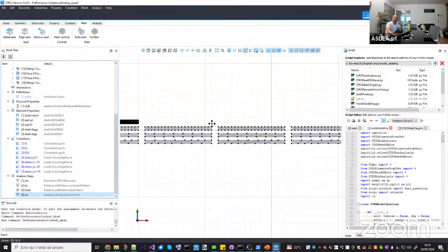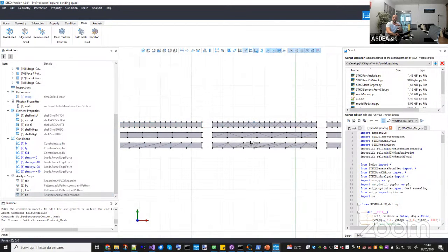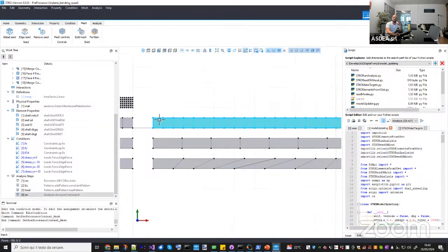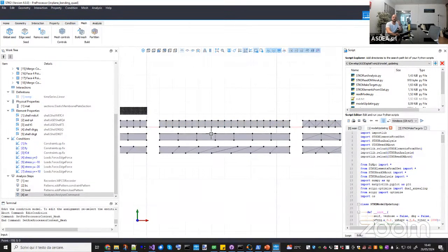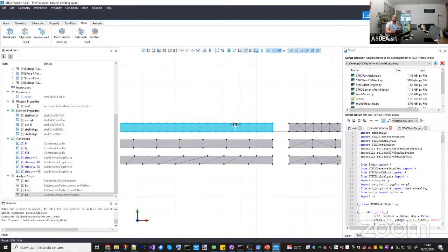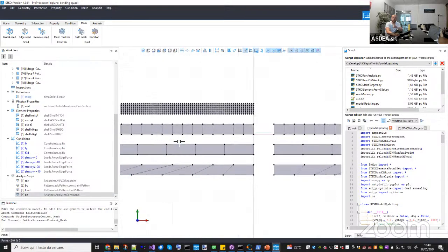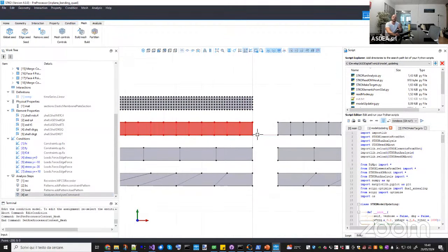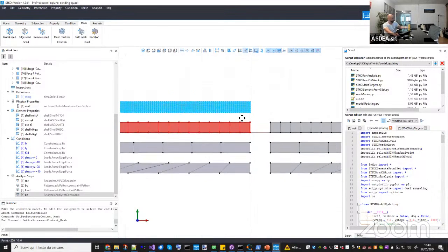These are the meshes. As I said, I prepare here, I'm only comparing the distortion, but I'm not using a very fine mesh, just because all these formulations are able to give an exact result, even if the mesh is coarse. But this exact result will get polluted as you deform the mesh, okay? With the shell MITC4, which is pure displacement based, you will never be able to get an exact result with only one element. You need a discretization. Why? Because it has a linear displacement, an almost constant stress state, so it is not able to represent bending properly. Okay, that's why you need a finer mesh.